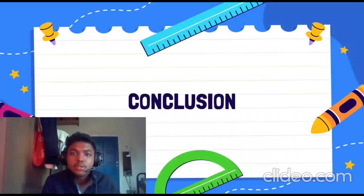Moreover, JKR uses the plate bearing test to carry out the soil investigation on the construction site. This helps us find a suitable foundation, evaluate the bearing capacity of the topsoil, and find any possibilities of settlement under the point investigated. This contributes to the fact that the building was planned to be built on a shallow foundation.